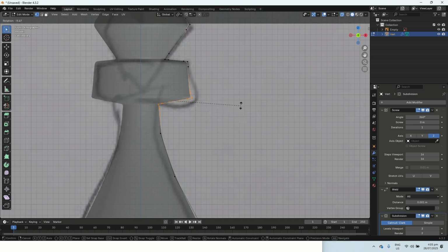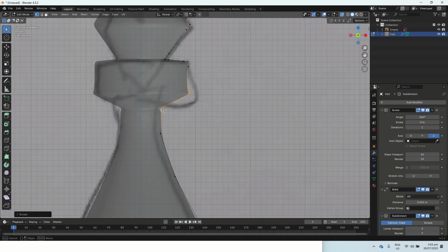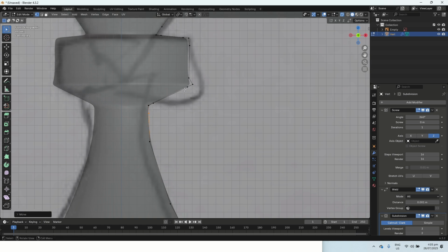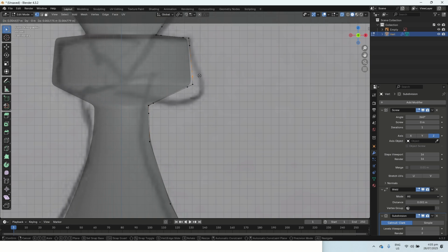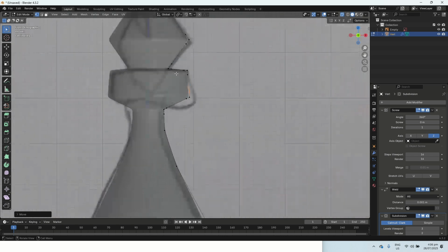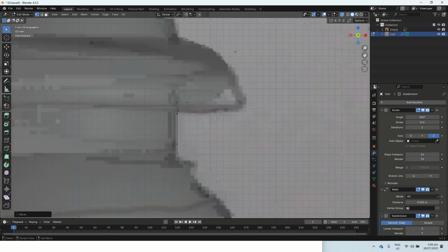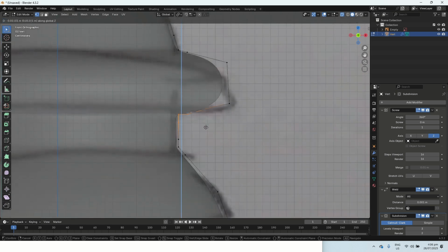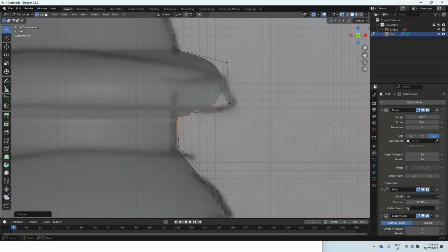You could also just manually rotate it to something like this, and that will be fine. It won't need supports. So as long as it's somewhere between 30 degrees and 45 degrees, it should be fine. I don't need to do the same on the top side. It's only these overhanging parts that require it. So this part here as well, just moving it down a little until it's got that 45-degree to 30-degree angle. Oh, what's going on here?